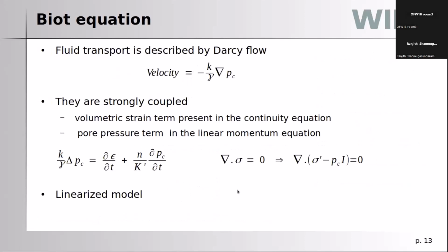Some of the features of the Biot equations: in the fluid flow transport, the velocity is described by Darcy flow, which means it is directly proportional to the pressure gradient. You can see that the Biot equations are strongly coupled. We have the volumetric strain term present in the continuity equation, and the pore pressure term present in the linear momentum equation. And this is a linearized model.